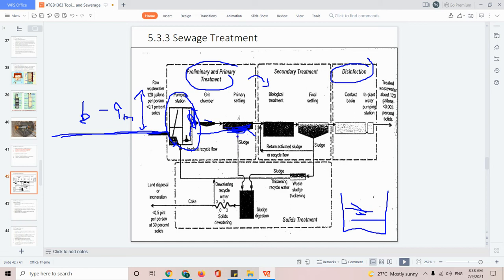So usually when we have a primary, you remove it to a sludge thickener or sand drying bed. This is something we call a waste sludge thickener, but we can also call it a sand drying bed. It's essentially just a structure with sand, and then we let it dry. Some sort of like a baking, because our weather in Malaysia is so hot. We can allow the sludge to further dry, and then after that, the sludge can be removed to become fertilizer.